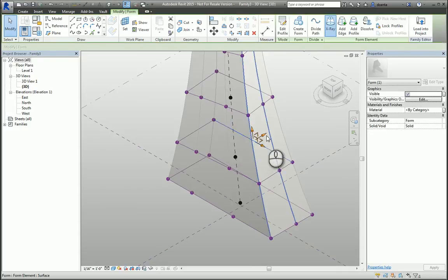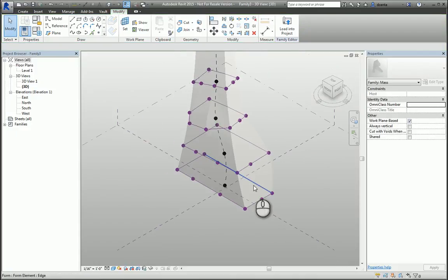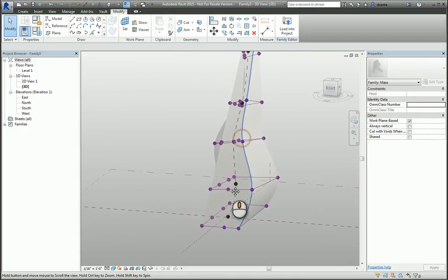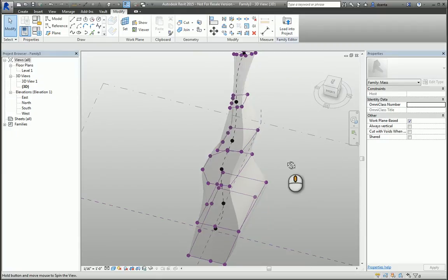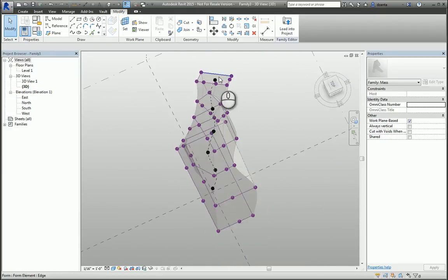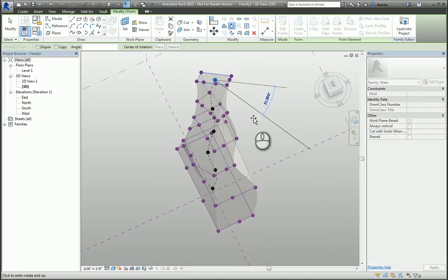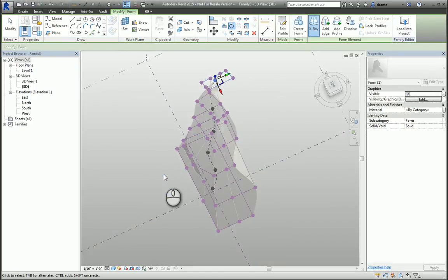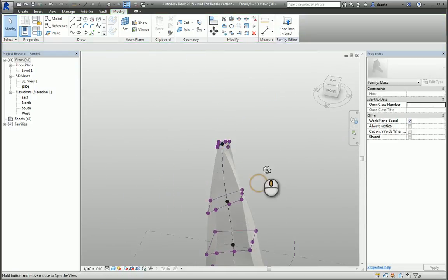And then you'll start to see how what you're building and why you're building, how things get shaped and adjusted just by picking and pulling on certain vertices, on certain edges, or even the faces of an object. If you hit tab several times in sequence, you have the ability to pick not just edges and vertices, but faces, and then you can start to do things like twisting the faces. Okay? And it gets very interesting when you start playing with this set of tools.